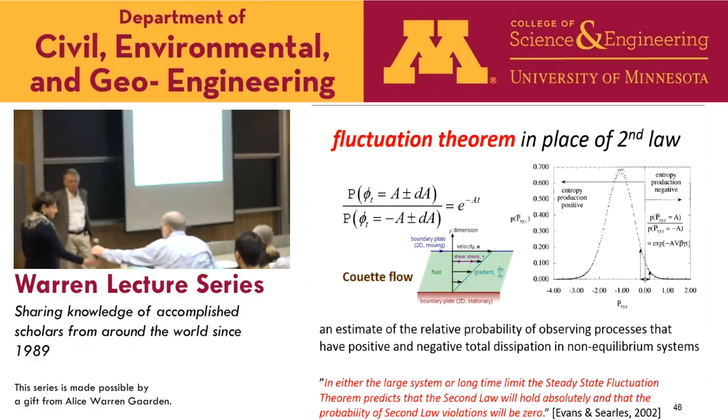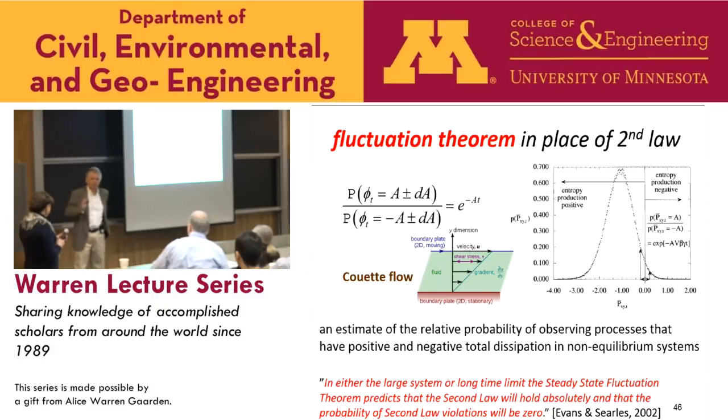Yeah, so the Hill condition is stated for volume averages. For one realization, if I do it over an ensemble, then I have statistical averages on top of that. So first of all, I do it for a typical element of the ensemble. One can study this just for one typical element, with ever bigger windows and boundary value problems. And then in principle, I have to do Monte Carlo, or maybe theoretically something is possible.